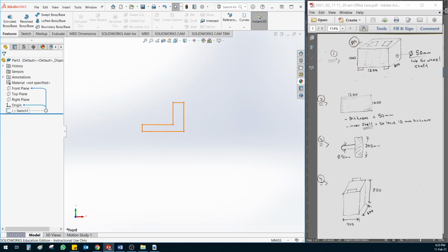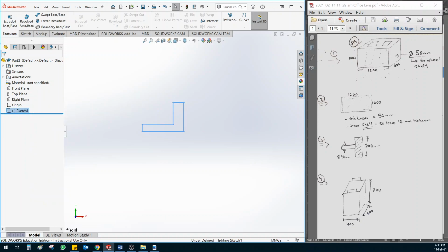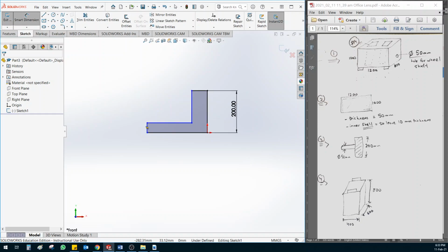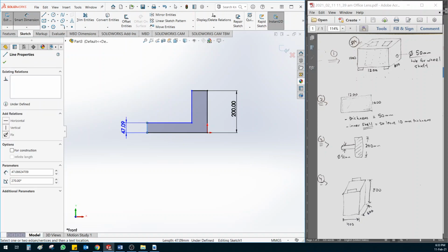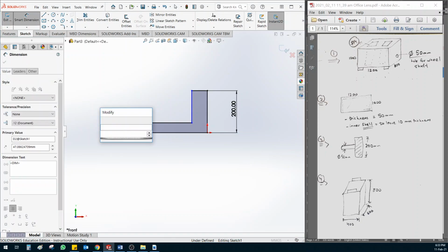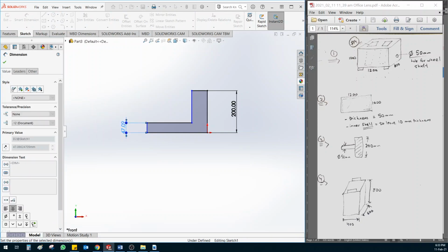Once I change the units, it exits the sketch. So I need to right click the sketch and click on Edit again. Okay, 200 here for my wheel, and my shaft is 50. And half of 50, I should give here 25. The length of this line should be 25 in order to be half of the shaft. And then this will rotate to give you the full wheel.